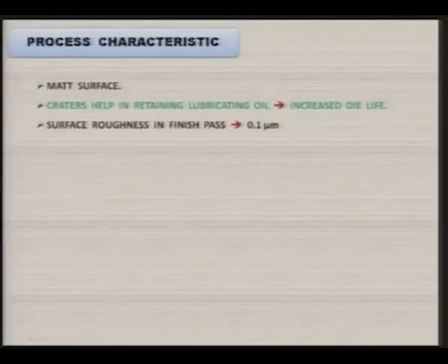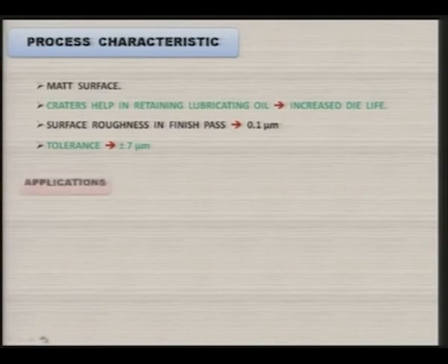Surface roughness in the finished pass may be achieved as good as 0.1 micron. Tolerance normally expected by the wire EDM process is plus minus 7 micron.